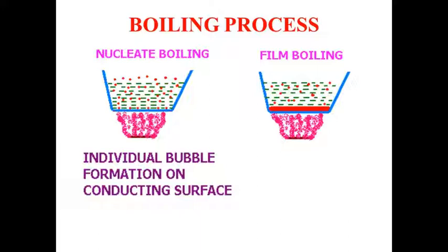So when we heat water in a vessel or container, if the heat flux which is supplied is within the regime of control, then we will find that first the bulk of the liquid is not receiving the total heat, only the layer of water attached to the container is getting heated, and gradually that water is spreading heat into the bulk of the fluid.